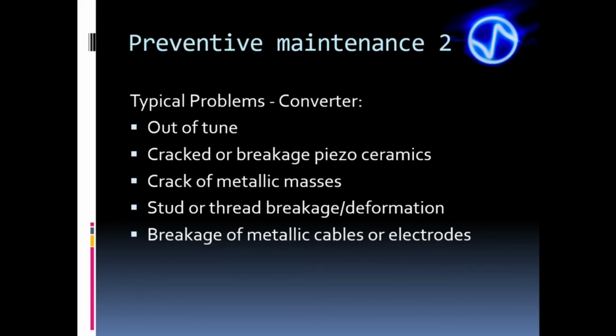Finally, if the problem is in the converter, we need to either replace or refurbish it. The typical problems of the converter are out of tune, cracked or broken piezoceramics, cracks in metallic masses, stud or thread breakage or deformation, and also breakage of metallic cables or electrodes.